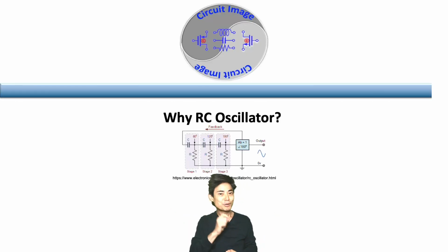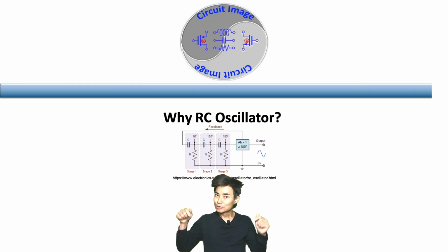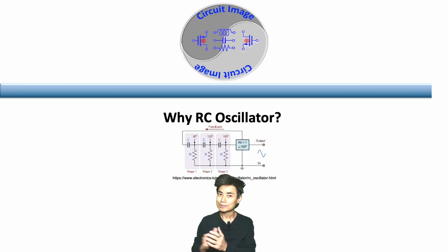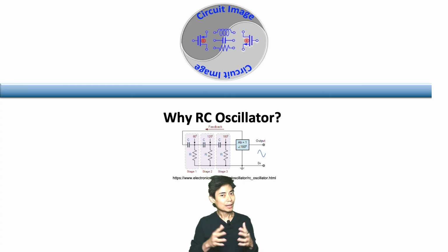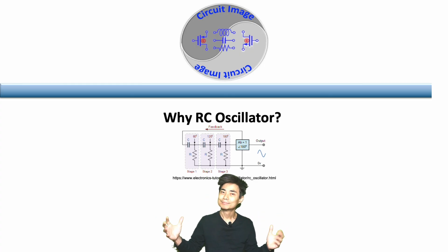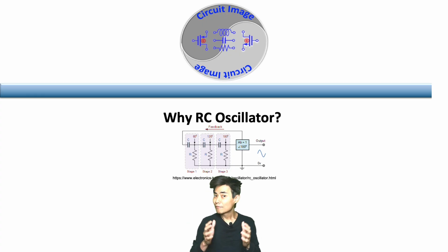Let's start with a simple question. Why even care about RC oscillators? In many chips, especially low power SoCs and sensor nodes, we need some kind of clock. Crystals work well, accurate, low jitter, but they are bulky and external. MEMS? Well, the MEMS itself could be smaller, but still not fully integrated, and could still be bulky after integration.